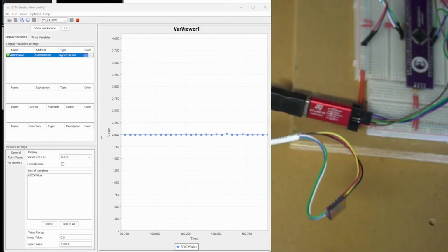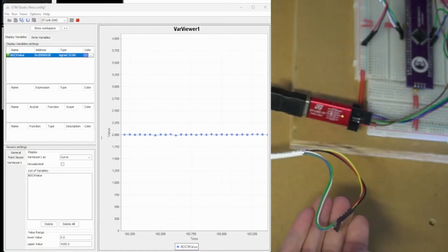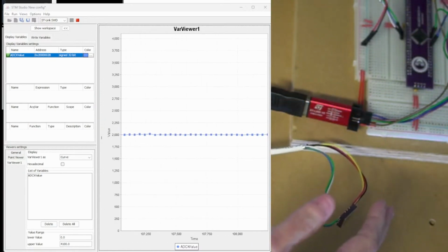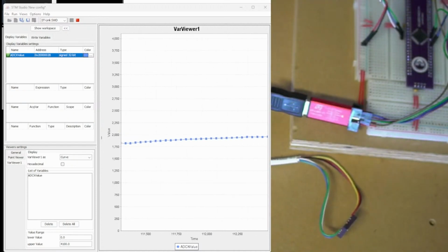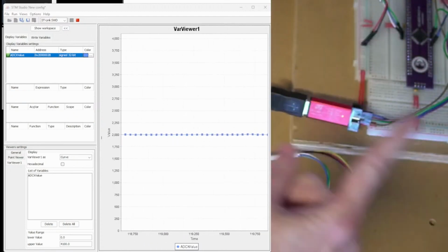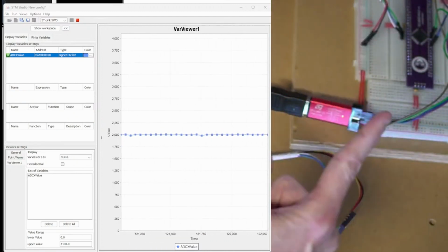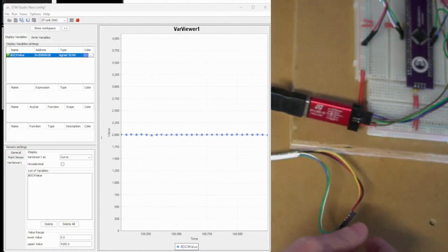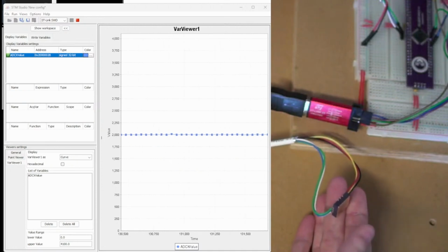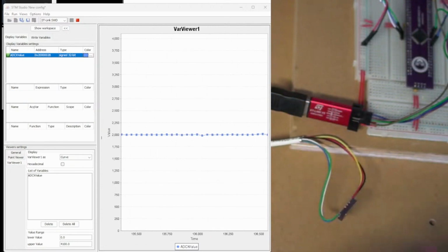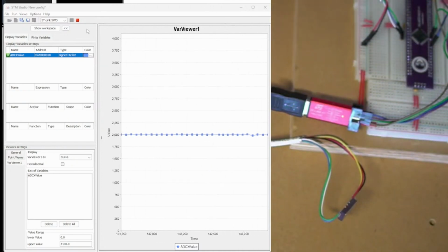Let me try a little bit more. This should be mounted on something more rigid. You're going to see that it's going to cause ringing internally. The piezoelectric structure in here is going to probably vibrate until it gets down to 0, as you can see there. So you can see that there was ringing. It's kind of like a transient response. A transient response is like this: it starts big, and then it finally settles. That's also called ringing. If you have this mounted on a good substrate, you'll be able to get a better response. So that worked. Let's go ahead and stop.